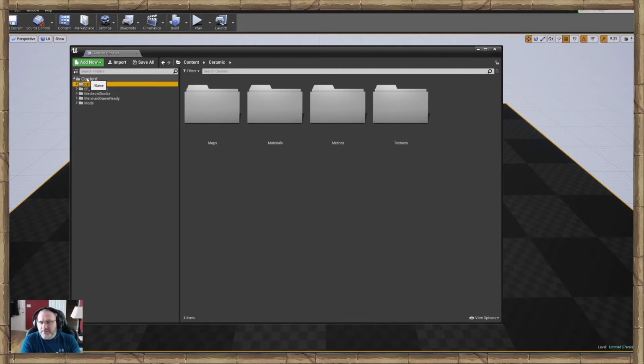Unreal Engine is very delicate when it comes to references. It needs to know the file path to get to that file, and if that gets broken, then your materials come out all gray, your textures come out gray, or you get the checkerboard look, because somehow the reference to that material or that specific item got broken. It can be blueprints, it could be code, so there are a lot of intricate working parts.